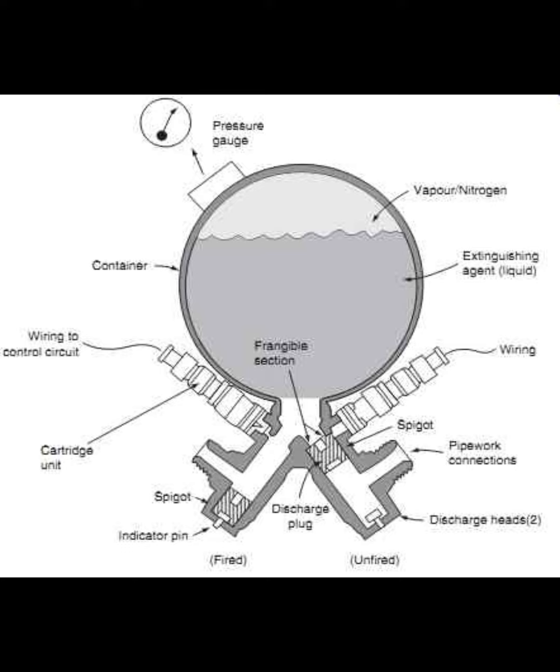What is the color marking used to identify fire extinguisher lines? Brown tag with a row of black diamonds. What method, other than the pressure gauge, is used to indicate low agent pressure in the container? Low pressure warning light in the cockpit.